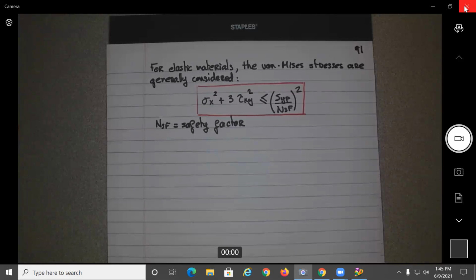Do civil engineers care about the weight? They don't care. So sometimes they take safety factors of 10 or 20, okay? If you design an aircraft, is it important to be careful with the weight? So they will take a safety factor a lot smaller. That's when you need to be a lot more accurate. But let's say you decide to take a safety factor of 2 or 3 or 4, all right? Then everything will change. Okay.